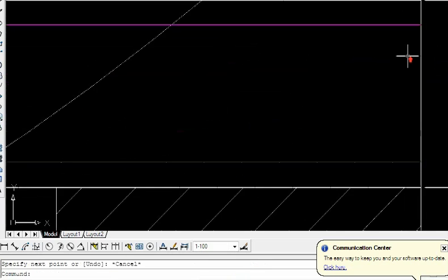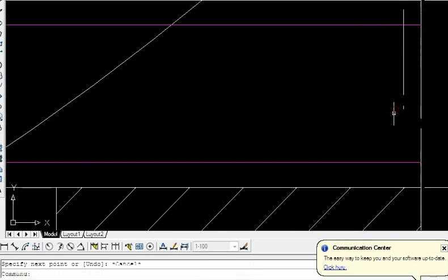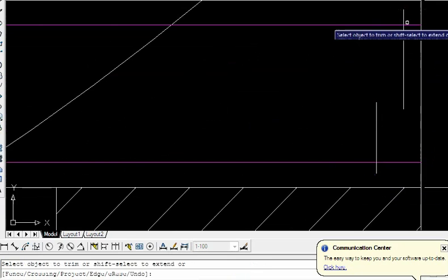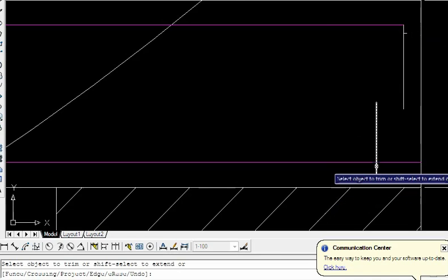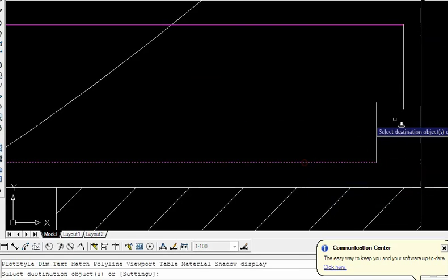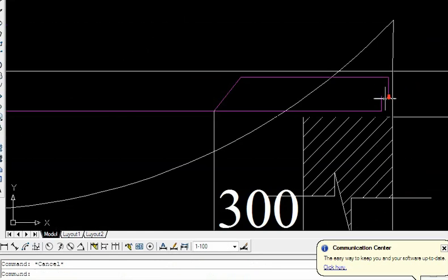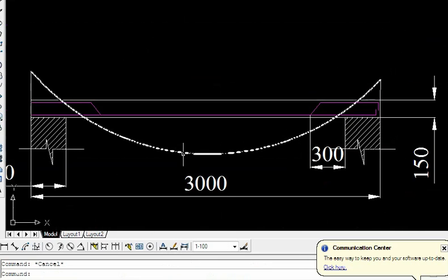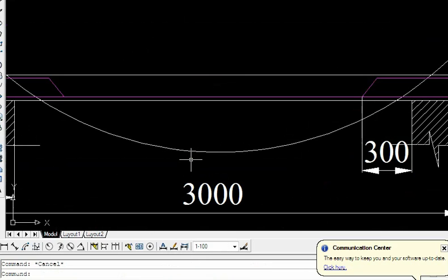So which bar will be bent here? How will we come to know which bar we should bend, which should not be bent here? The main bars, both are main bars here. So only alternate bars. We can see from the diagram, it is very clear that maximum moment is there at midspan, and the moment at the support will be half of the midspan. So whatever bar is provided at the midspan, half of that bar should be provided at the top.